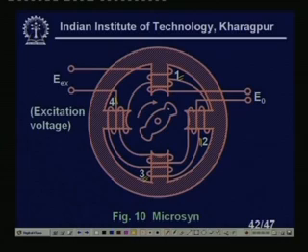Now, in this particular position, which I have shown, this is a rotor, this is basically made of iron, this is a null position. Why it is null position? You see, in this particular position, the reluctance between the iron and coil 1 and between the iron and coil 3 will be exactly balanced, because if the reluctance is large, obviously the inductance will be small.